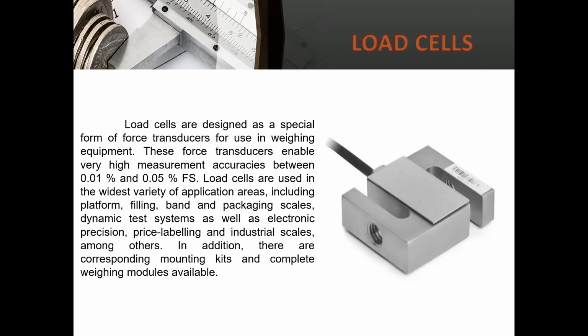Load cells are used in the widest variety of application areas, including platform, filling, band and packaging scales, dynamic test systems, and so on. Among others, Wika provides you with all typical and widely used load cell geometries such as bending and shear beam load cells, S-type load cells, and compression force load cells, just like I said a while ago. In addition, there are corresponding mounting kits and complete weighing modules that are available in Wika.